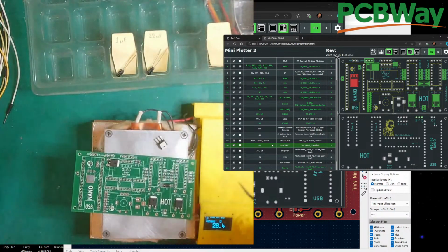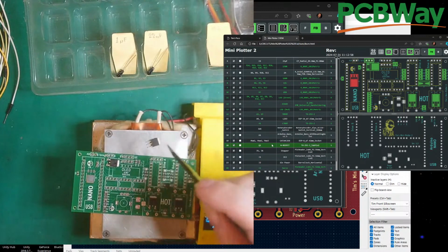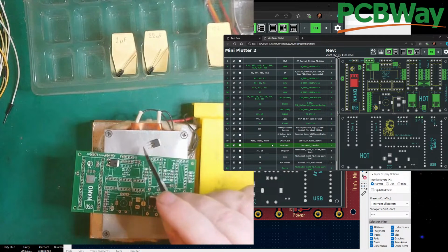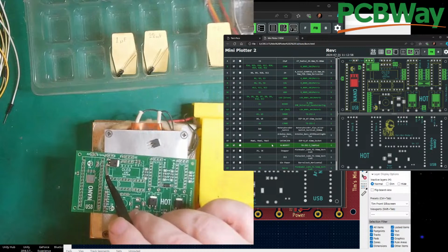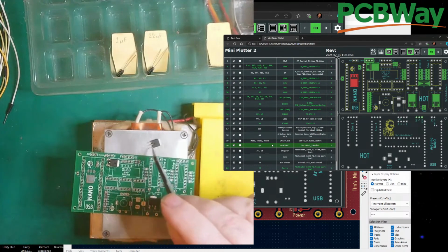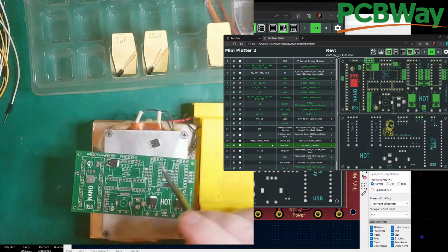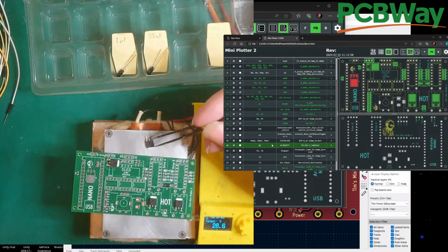What I've done here as well, you can get it in this package, but the MOSFETs I had, you see these pins look long, that's longer than these pins here. That's because these were the 3 straight pins, and I've just bent them to match this footprint. So use what you've got, and that's what I had.